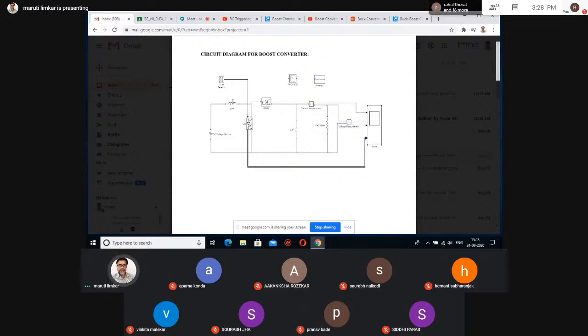Only the inductor remains. So in the properties, you have to substitute R is equal to 0, and the reactance XC is equal to 1 upon 2 pi FC. Okay, C is equal to infinity, that will act as a short circuit. So you have to select R is equal to 0, C is equal to infinity. So your remaining element is only the inductor. Depending upon your requirement, you have to select the value of the inductor.